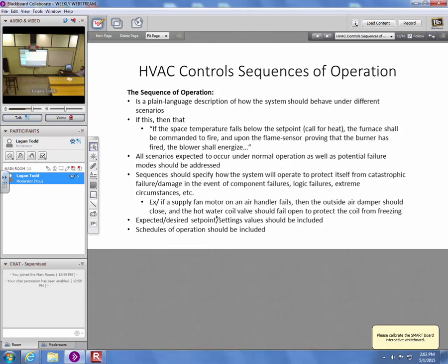You can have, and this kind of fits with the cherry, you said cherry switch? Yeah. Well, I don't know that brand of switch, but sometimes these damper actuators, especially on an outside air damper, will be installed with a feedback loop so that it can tell the control system whether the damper is open or closed, or an end switch or something.